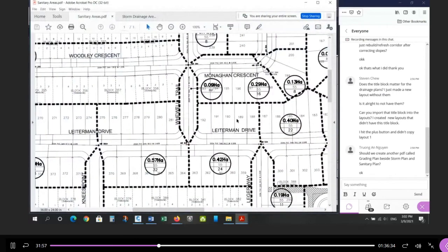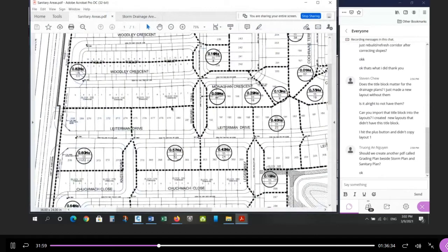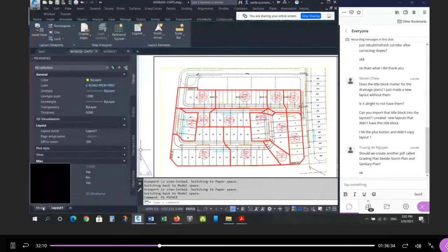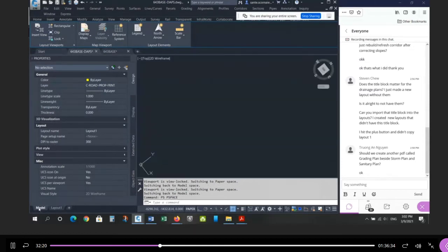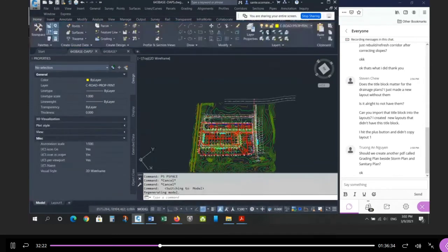Okay, now you'll notice I don't have this line type, right? This hidden line type. That's fine. Just make it a continuous line. Okay, that's hard to achieve if you're not careful with the line type, because when they overlap, remember these polylines all overlap each other on the edge, so the line type sometimes cancels itself out. Okay, so you have to be careful. I can show you that.